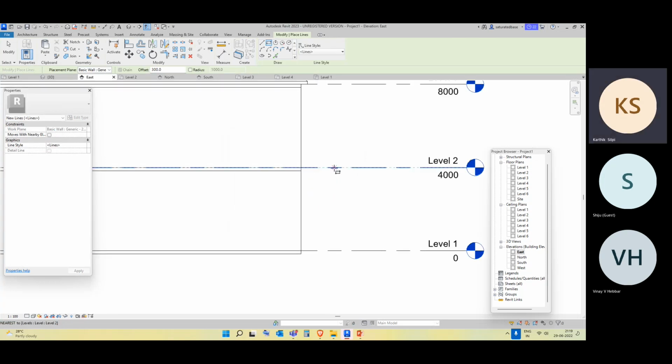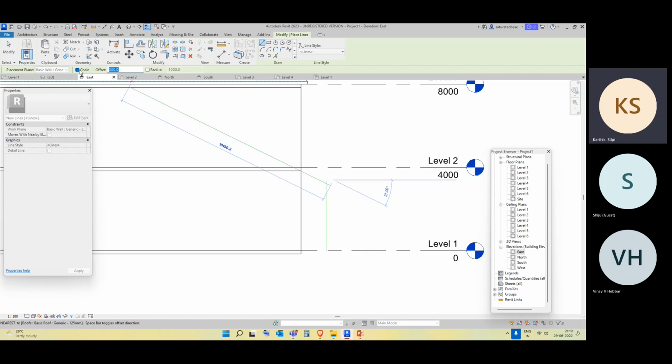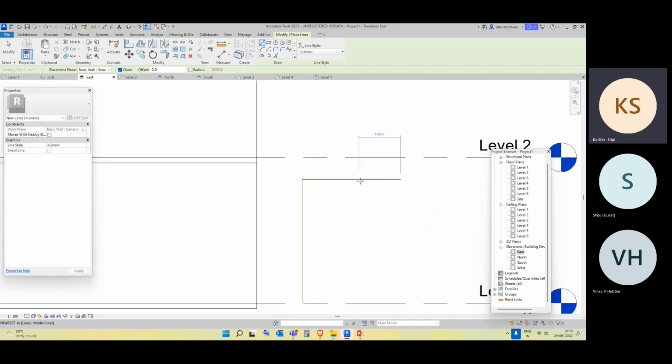Whatever level we are going to take from the ceiling plan. Let's say this is, let's take this line. So this is 4000 mm. So if your ceiling plan is a 3000, starts at 3400 mm, right? Yeah, offset is 0. This part, this is where our whole MEP will be functioning.